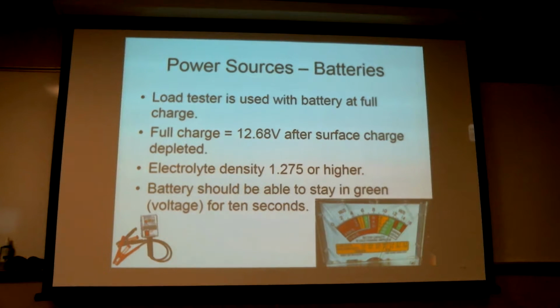If it will charge, the next test is: it's charged, so load test it. If it passes the load test, maybe it's okay. Start checking for other problems: the glove box light doesn't turn off, or the master switch you think is off really isn't.